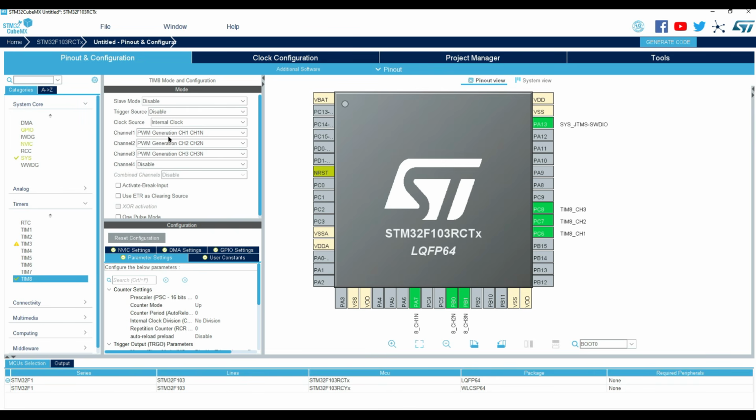And why is PWM required? You cannot control the speed by just turning the voltage up and down. BLDC needs precise voltage control and phase timing. Only timer PWM can give fixed frequency, accurate duty cycle, smooth speed and torque, dead time protection, and standard behavior.